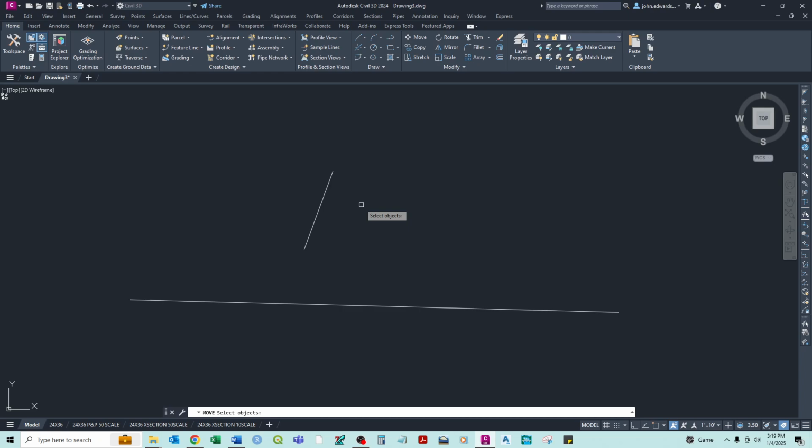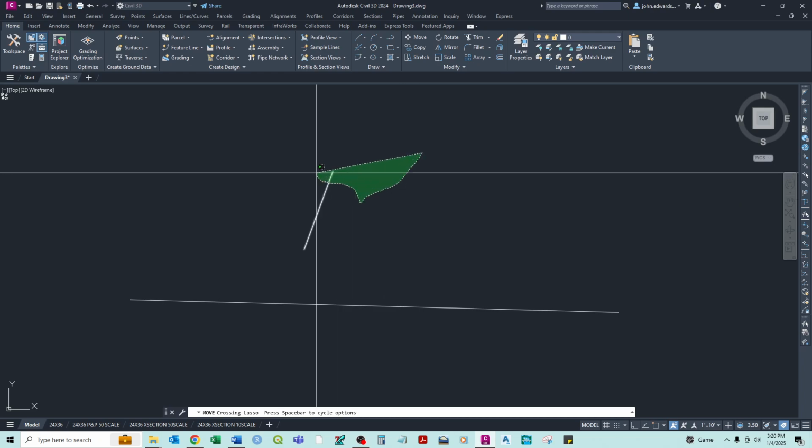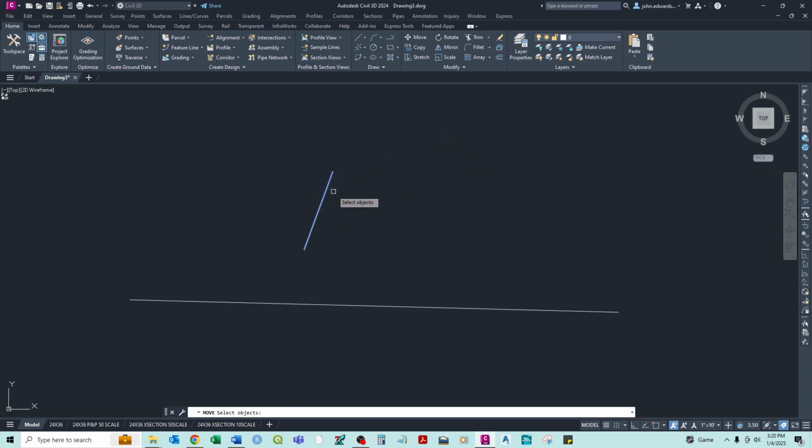Your full crosshair has gone away, and now you're at just a little selection box. This is common with a lot of these other commands. Now you see it tells me right next to my pick box, but also in the command line, it says select objects. So I hover over there, select it. Again, I could use the different selection processes, same as before, but I'm just going to click it. Now what? You see there's nothing else for it to do. When you're within a command, sometimes there are multiple steps. To cycle to the next step, we either hit enter or right click.